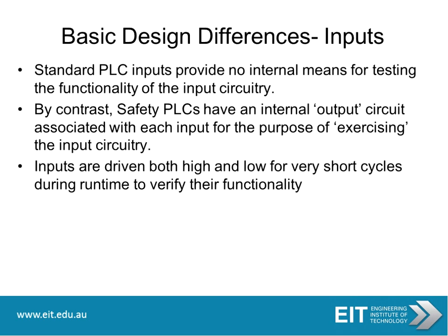Then if we look at the differences in terms of inputs, your standard PLC inputs provide no internal means for testing the functionality of the input circuit. By contrast, your safety PLC has an internal output circuit associated with each input for the purpose of exercising the input circuitry. So your inputs are driven both high and low for very short cycles during the runtime, just to verify their functionality.